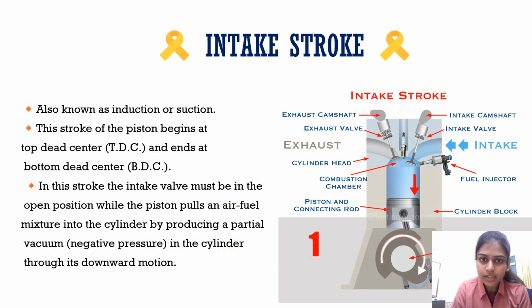Our first stroke is intake stroke, also known as induction or suction. This stroke of the piston begins at top dead center, called TDC, and ends at bottom dead center, called BDC. In this stroke, the intake valve must be in the open position while the piston pulls an air-fuel mixture into the cylinder by producing a partial vacuum or negative pressure in the cylinder through its downward motion.